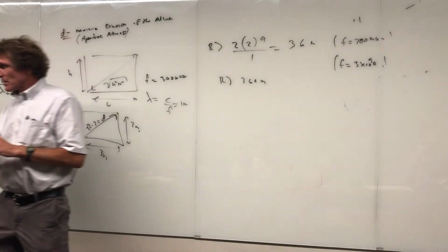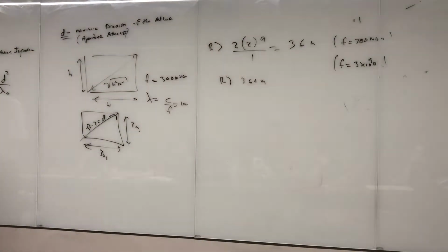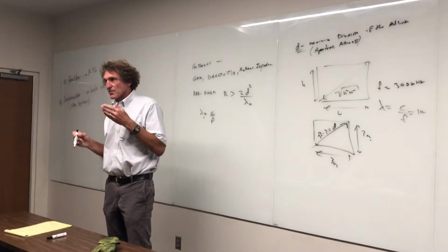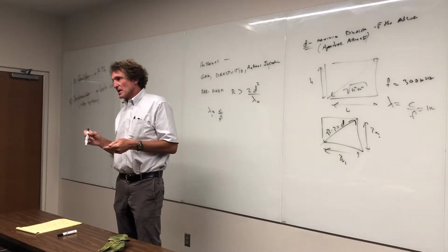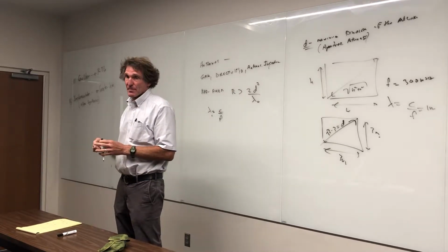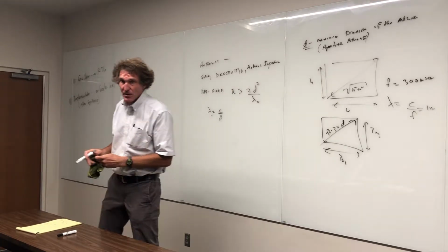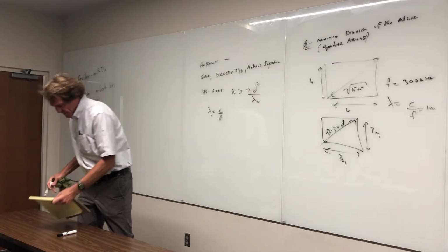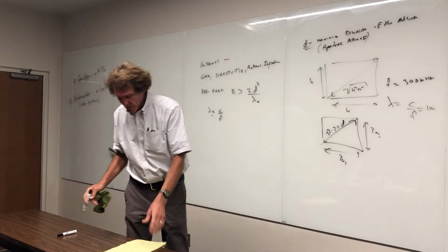And we'll get this from the equations later, and it's just something to be aware of. You don't realize how sensitive that is. But you go from 300 megahertz to 3 gigahertz, an order of magnitude, and all of a sudden I have to be an order of magnitude further away, basically, which is important to understand. Follow me, guys? All right. So we're in the far field. Now, when we talk about antenna,